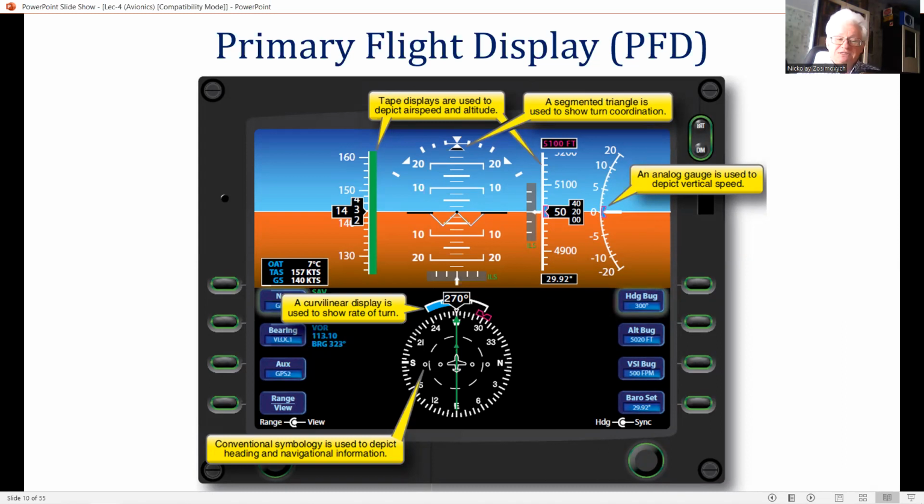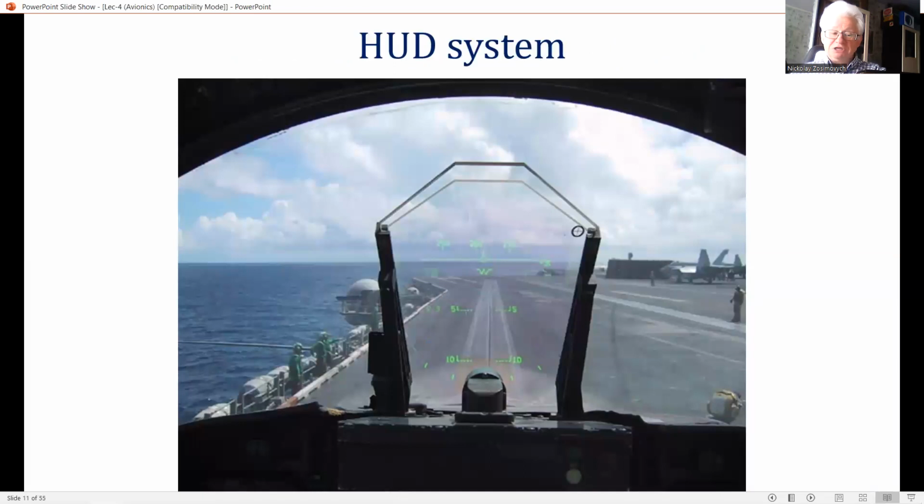Dealing first with the question of integrity, the display of primary flight information must meet an integrity figure of 10 to the power minus 9 for the probability of occurrence of displaying potentially misleading or hazardous information. A single unit HUD system, combined processor, symbol generator, and display, can meet this integrity figure using the monitoring techniques described a bit further on.